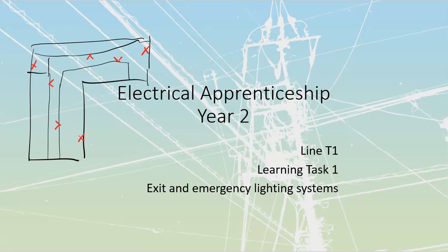You'll see them, generally speaking, in hallways, not so much inside of personal spaces like offices. Most of you could find your way out of your bedroom with your eyes closed. Most people that work in an office are going to be the same. They can find their way out of their personal office with their eyes closed, but the rest of the hallways could be a little bit more difficult. Same with public areas like washrooms. You don't have natural light in most washrooms because you don't want a window. So you're also going to have exit lights inside of those areas.